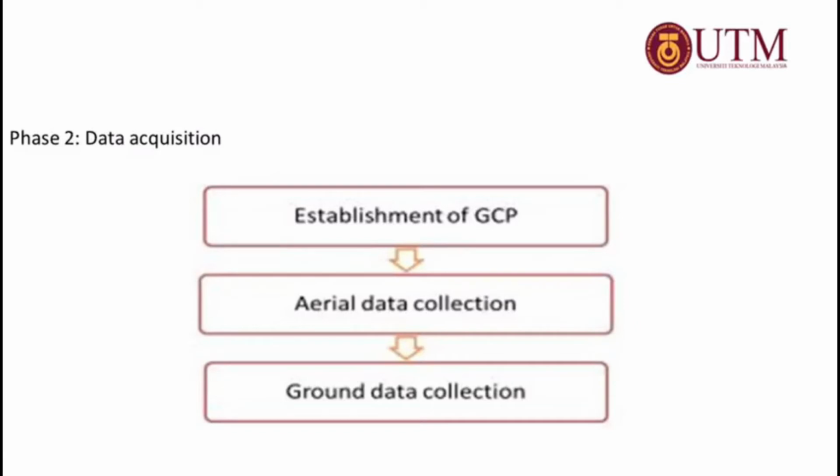Ground data in this study was collected by using geodetic laser scanner as it has the advantage of geodetic positioning in the instrument. GLS is a type of terrestrial laser scanner that allows traversing. By using GLS, it's easy to position the laser scanner by inserting the known coordinates of the points and collect the point clouds of the building. Laser scanner was used to collect point clouds of the facade of the building. One of the limitations of using laser scanner is it cannot collect the surface of the roof of the study area.